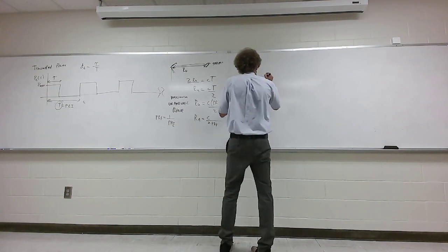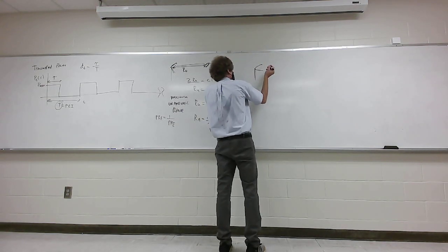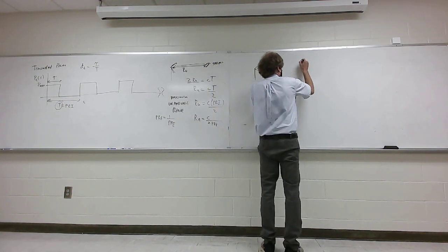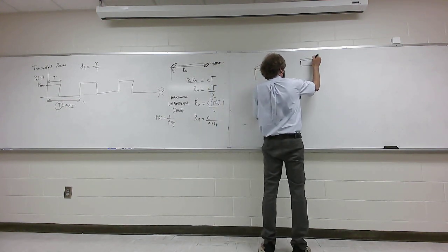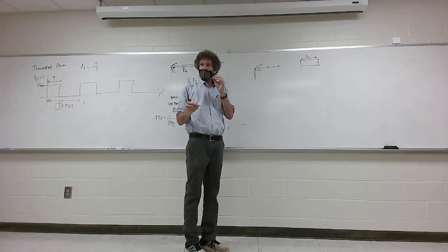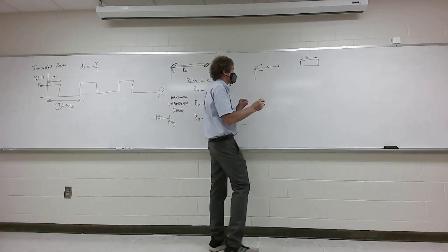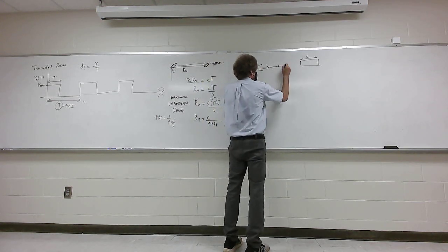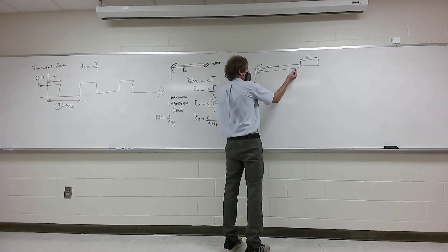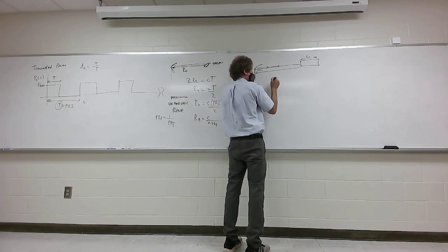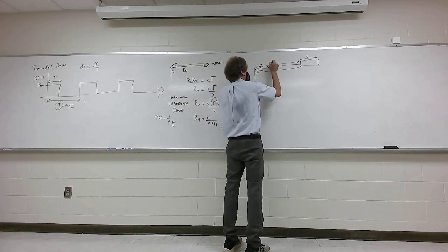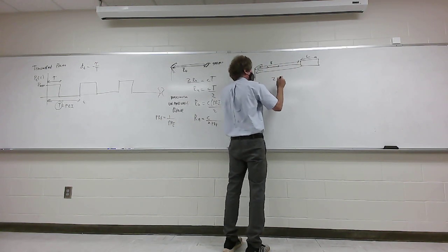So what is range resolution? Don't write this down, just listen. So I send out a signal, and I have a target of some length L. Y'all follow me? I'm giving you the dimensions, radial dimensions. All right, this signal goes out, hits, comes back. So the shortest round trip would be, and I'll call this distance to the front end R, the shortest round trip would be 2R. You with me?